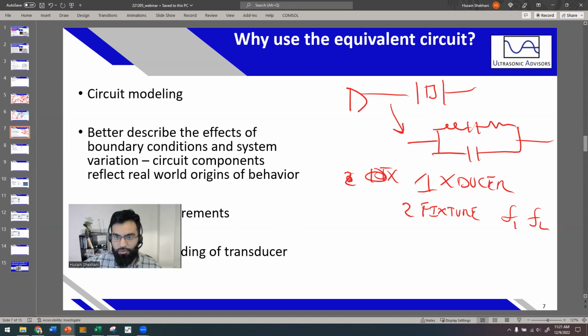But then you say, hey, let's do this analysis, and through the analysis, you found that, let's say, your inductance was different. So you figure that, hey, this is maybe a mass loading effect. So what might in these two fixtures cause that? Or you find a difference in your capacitance. So you feel like, okay, there's extra stiffness being added, or there's a difference in your resistor. So just changing the resistor changes the damping factor, or changes the quality factor, which can shift the results all in and of itself.